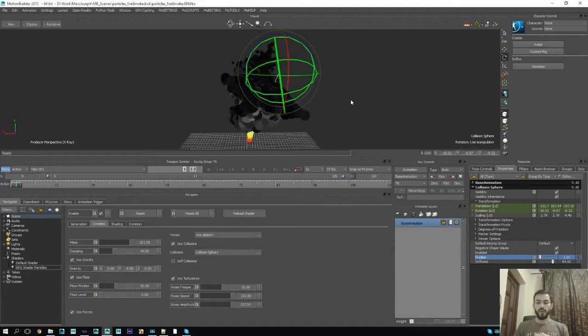and we want to do some effect on particles, but we don't want to make too much influence, so we can control the amount of influence with the softness parameter. So the bigger softness means the less influence the collision will apply to particles, and without softness the collision will hardly collide and pull the particles out of its volume.